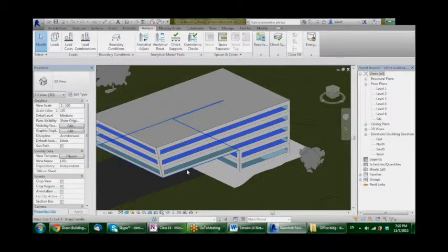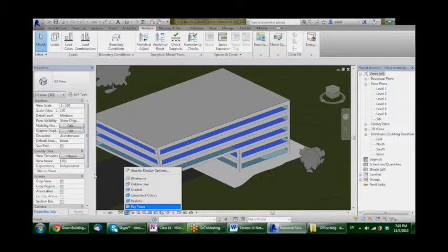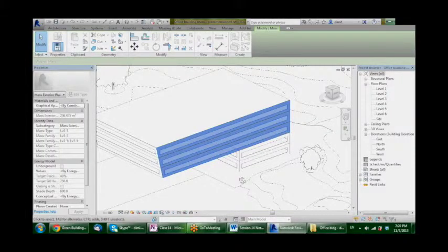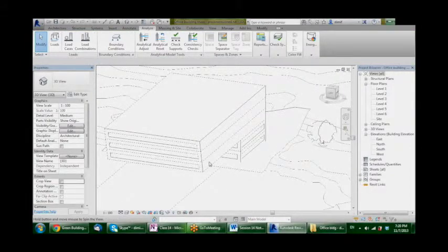So go ahead and pick a surface that you want to fully customize. Delete all windows, so this surface is blank. And now the way to do this is you have to divide the surface of that mask. So here we go. You select your mask and you hit edit in place.